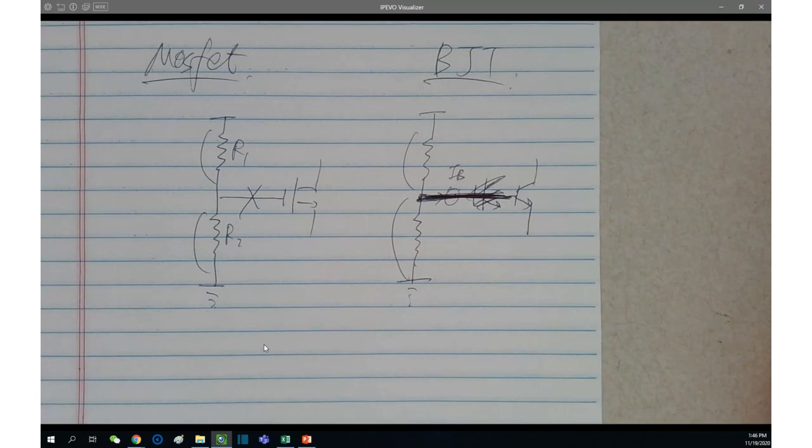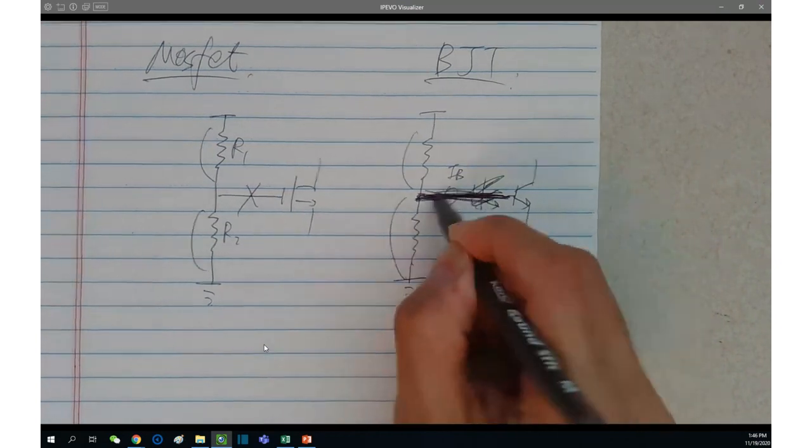The current and voltage dividers, you need to identify them first. This must be a single loop circuit or a single node pair circuit. Then you are able to apply the voltage and current divider. This is the knowledge back in Circuits 1. So here we can't do that. This is not a single loop because of the existence of this path.